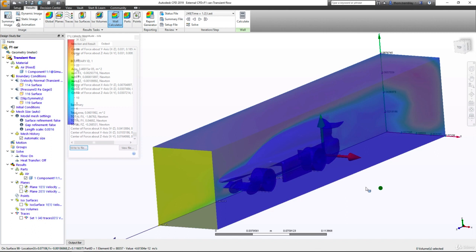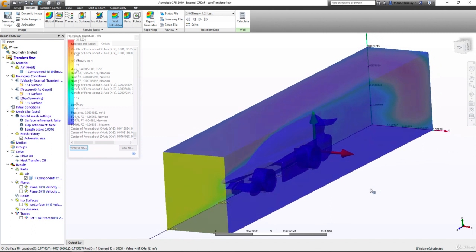An important note is that if you return back to Fusion 360 and update your design model, your simulation model will update as well. That change can then be used to update the CFD study without having to update any of the boundary conditions. This will allow you to quickly iterate your design and quickly test out the aerodynamic properties of your car as you develop the design.